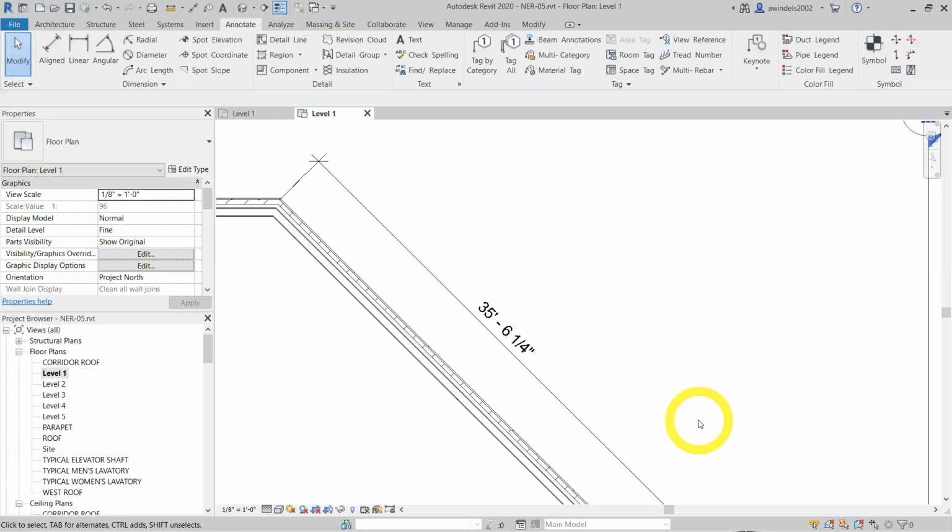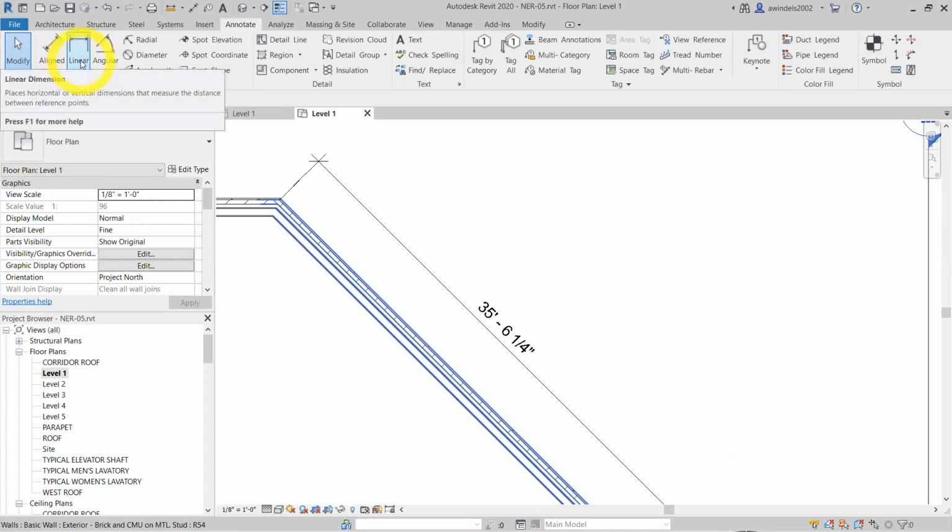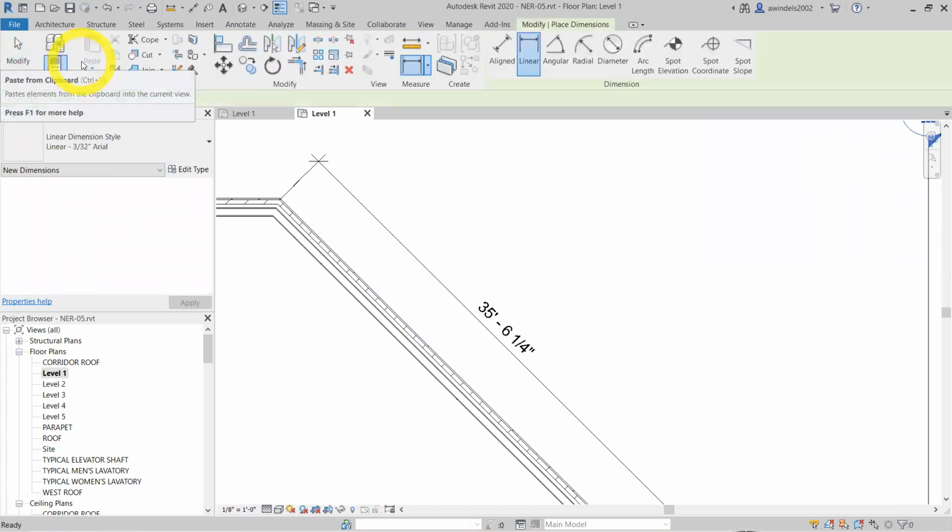If you didn't want to see it to that degree of precision, I'm going to do a linear dimension now, which they're used a lot less frequently. They only go in X or Y directions, just like the name says. They don't go in a straight line in one of the two ways. So we'll show you a good application of one here. So go to the Annotate tab, pick linear, pretty similar spot.